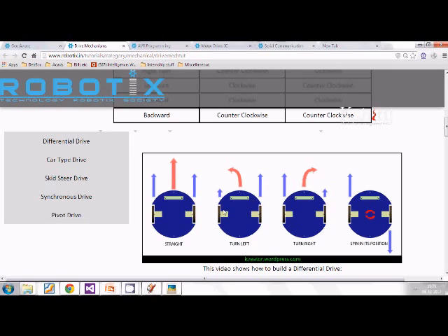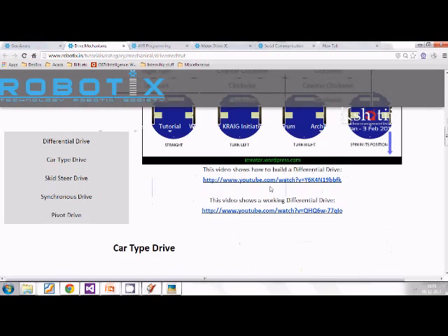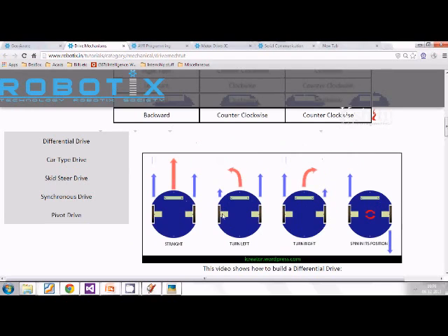Another thing you can do is have the left wheel move backward instead of forward, and that will lead to a turn about the center. This is called a zero radius turn, while in the earlier case it would turn while still moving forward. If the two wheels move in opposite directions with the same or similar speed, the robot will turn about the center.